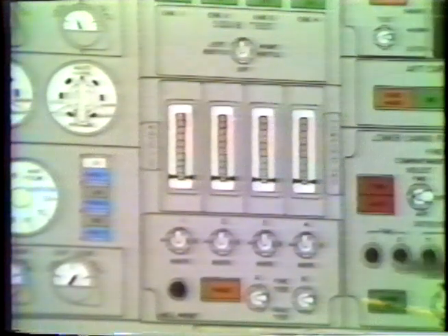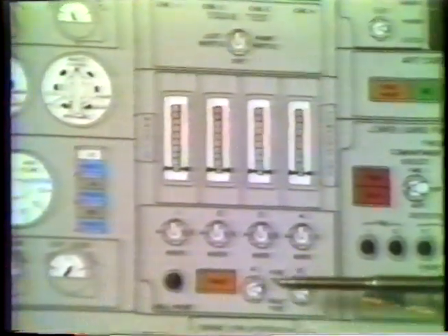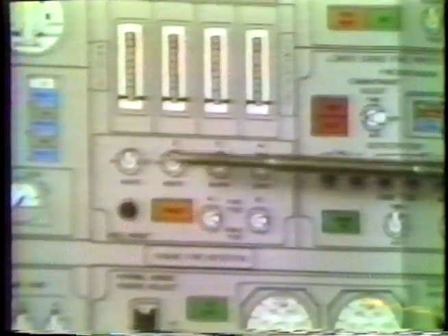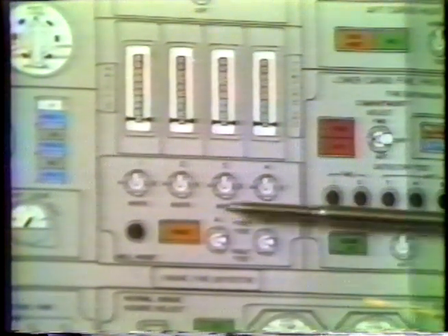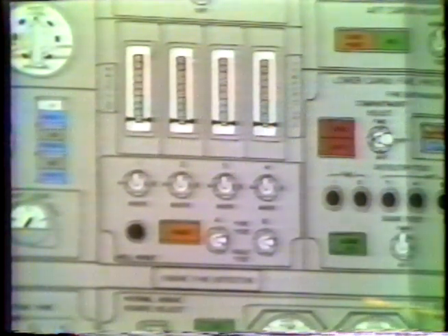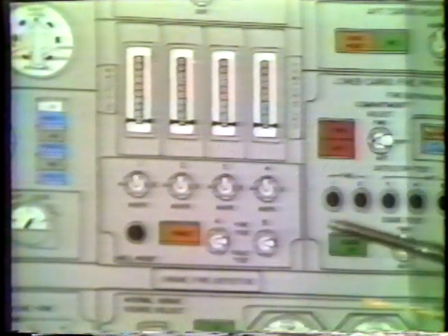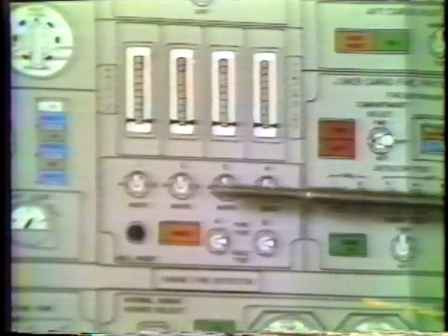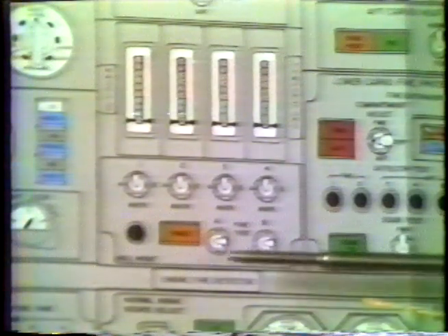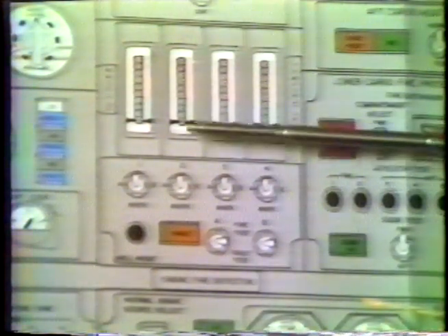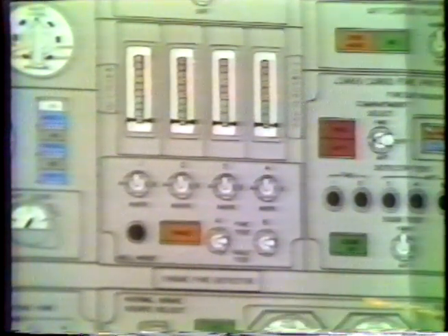When you do a fire test, to get a proper fire test, the switches in both the A and the B have to be moved to the test position to get the fire lights to come on. If you do one or the other, you'll get the fault light and no fire warning. By moving the switches to the down position, this simulates a fault and makes the pointers move to the top of the scale. This will not give you a fire warning, but will give you a fault light here and in the master annunciator.